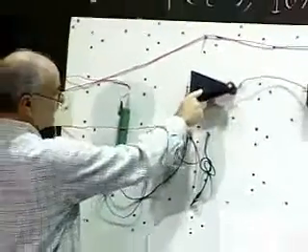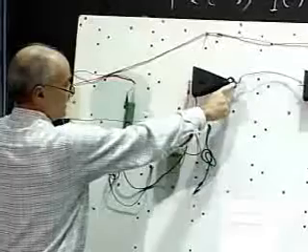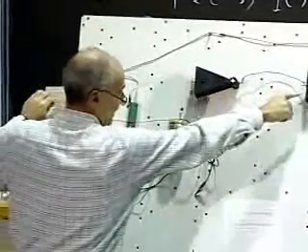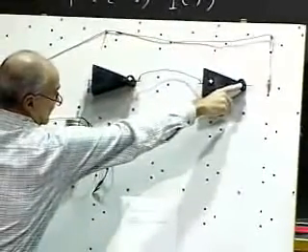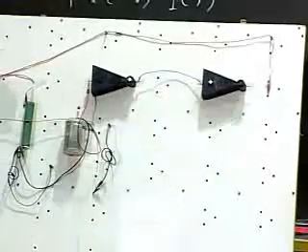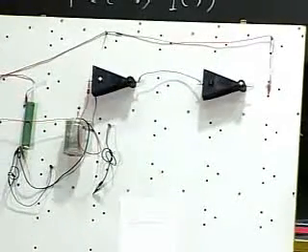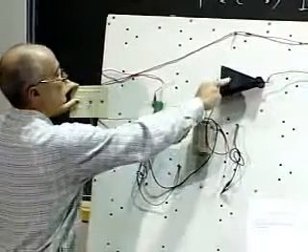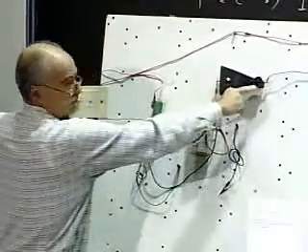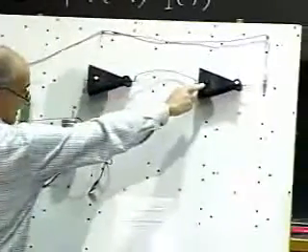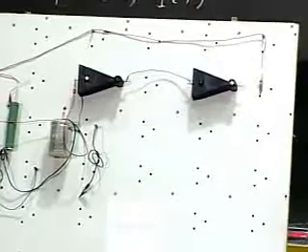As you can see, the input is 0, the output is a 1, and then the output of this inverter here is a 1. I have 2 inverters in series. Now I'm going to charge the capacitor. Okay, so I charged it to 5 volts. This lit up. This is off, of course. That's an inverter. This is a valid 0, producing a valid 1.